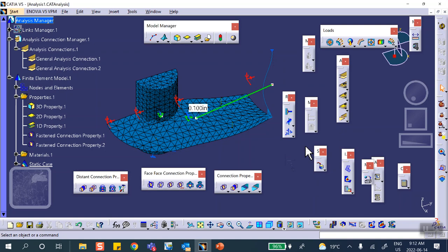For real life, then you have to be very careful. In other words, what is going on? One of the things that you cannot do like this is that this was a cable. If this was a cable, you cannot prevent that cable from bending anymore. Because when you do it point-to-point rigid, then you can go and release the degrees of freedom. So be careful. If I said these are cables, this is not going to do it. You have to do it point-to-point, rigid, and release the corresponding rotational degrees of freedom. Any questions here?